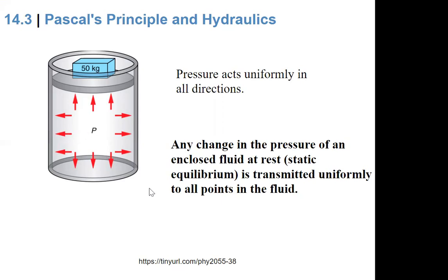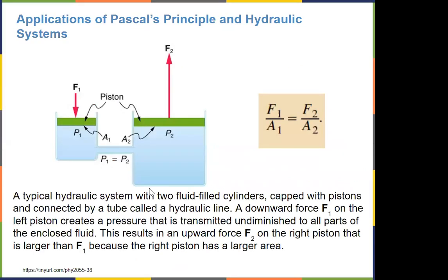Due to that, you can design a hydraulic device or system like this. On this end, you can have a small cross-sectional area as your input.